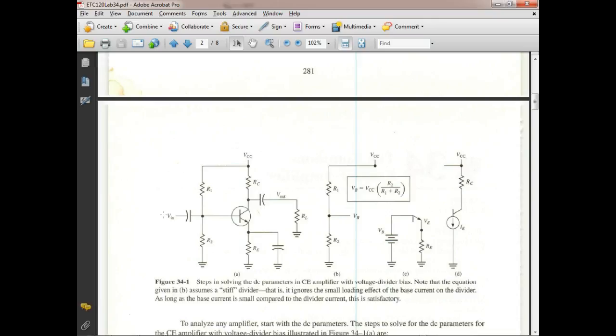So we had two people say, what's the advantage of a full wave over a half wave? They said, well, a half wave gives us 60 pulses per second, and so what would that have to do with a DC motor? A DC motor don't see 60 pulses per second. A DC motor don't see 120 pulses per second. It sees so much voltage, right? You understand? So what's the advantage of a full wave over a half wave? For the same secondary voltage, the full wave gives you twice the number of volts than a half wave does.